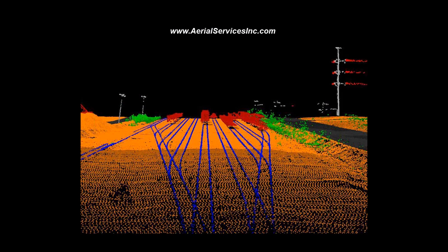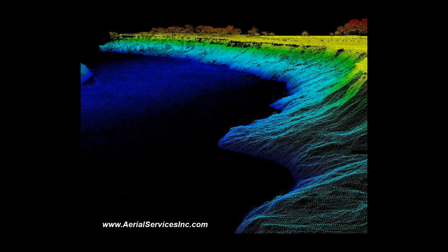The airborne, I'm going to fly at a 1-to-1 ratio, so at 500 feet above ground level, I'm going to have a 500-foot swath. At 1,000 feet, I'm going to have a 1,000-foot swath, ballpark. I'm going to fly a 60-degree field of view and have 20 to 40 points per meter. In a helicopter or fixed wing, I'm going to do probably 8 to 12 points per meter.